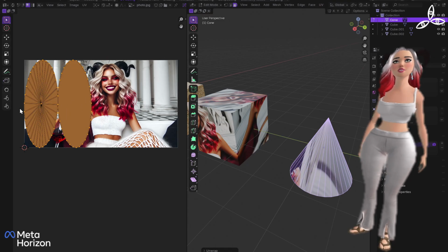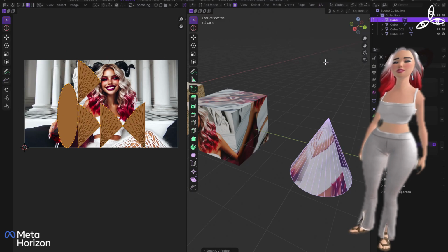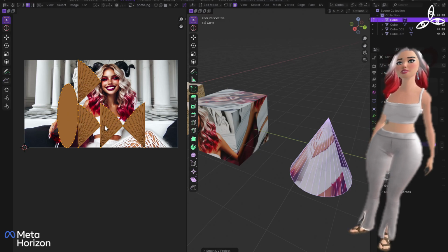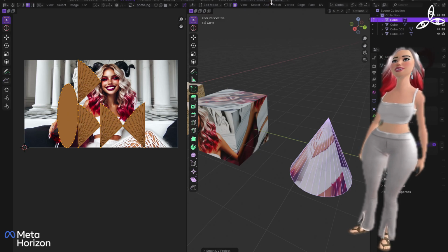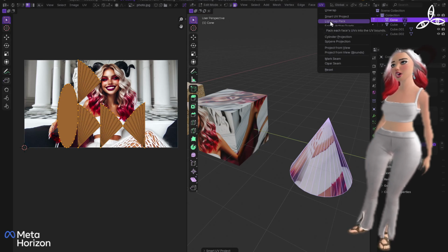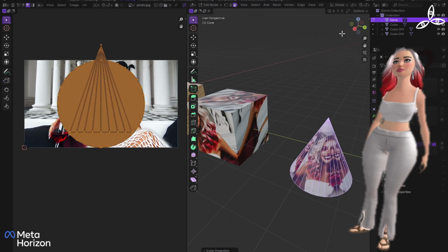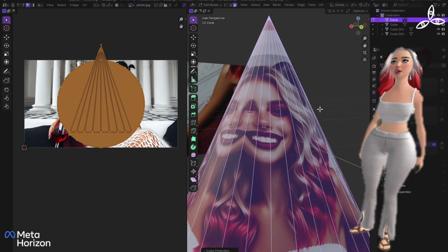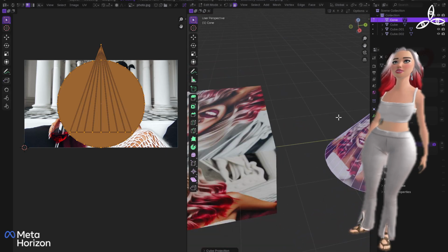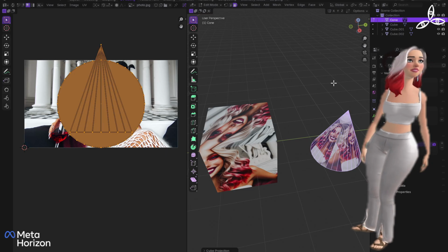Let's have a go at doing some of the unwraps on the cones. If I just do the default unwrap, what happens? Okay, so it just plonks two over there. And if I say Smart UV Project, what happens? Yes, it's actually split it into almost wafers, which is interesting. There's a lot of power behind this. It's quite specialist, so I'm not going to go into it on this course, but there is no one ideal way of doing this. So you actually got overlaps here using the cube projection. That's funny. Okay, so yeah, have a bit of fun with that.